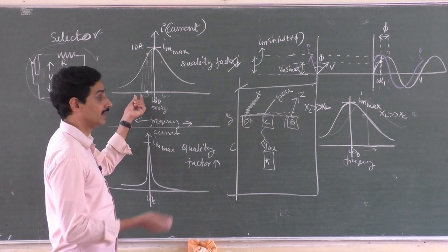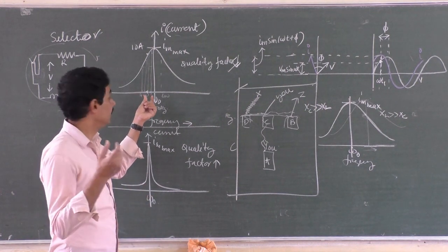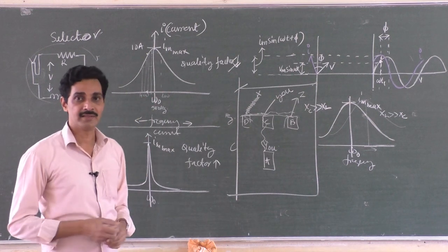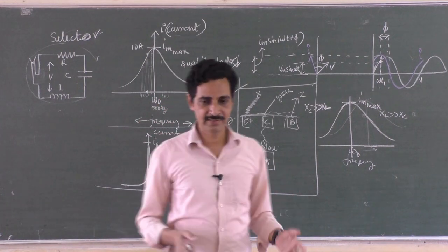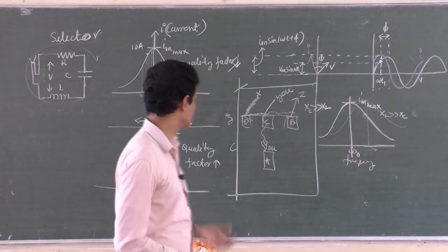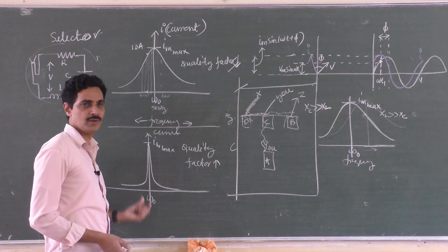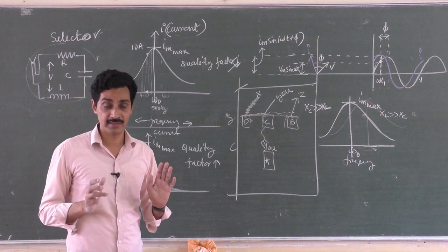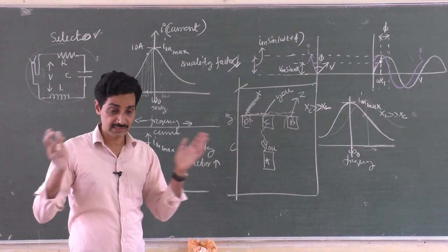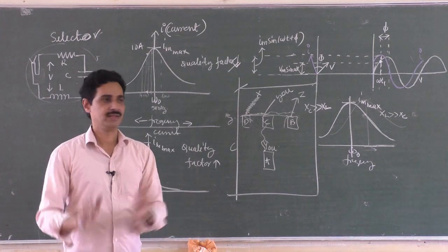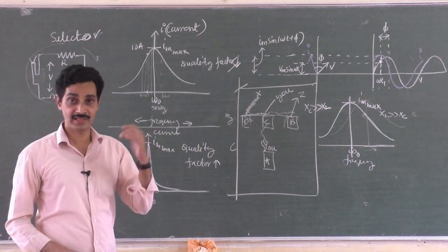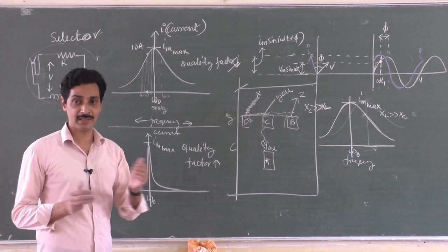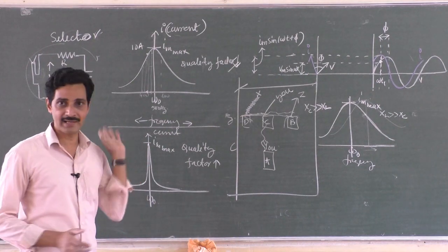It will start decoding all the signals from 400 Hz to 800 Hz. That's a very bad mobile. Whatever signals come, it starts ringing. That shouldn't be so. It should be highly selective. Only those signals which are sent for my mobile should be received. And signals sent to other mobiles, even if they hit my mobile, it shouldn't receive them. It should reject them. No current should pass through that resonance circuit. This is a rough idea. Actually, mobile communication is not so easy, remember. But the basic idea is this one.